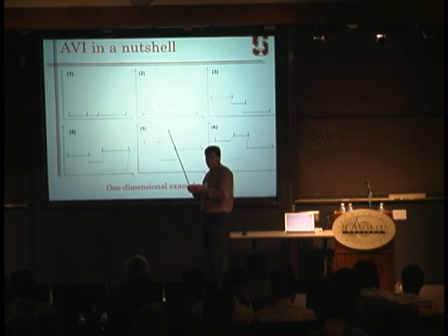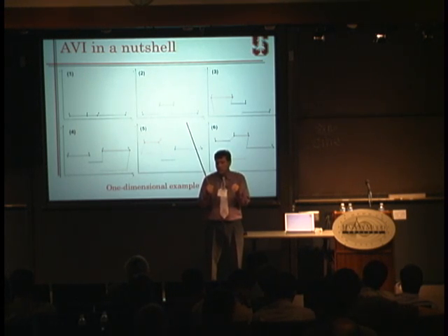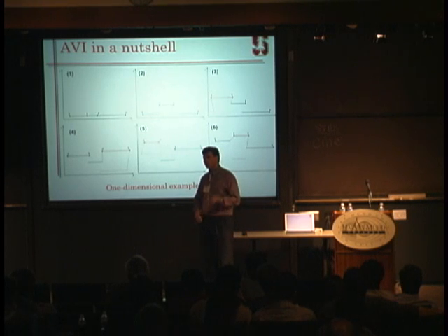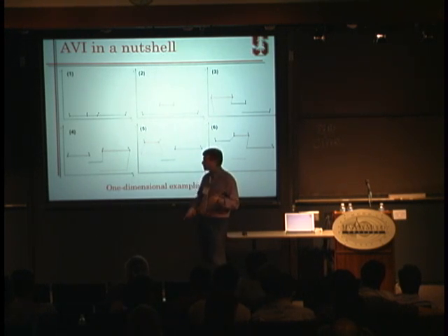At that point, you have deformed your element. So you have pulled the spring, and there will be forces that will try to restore the spring to its natural position. So you use those forces to kick the masses. It's like hitting them with a hammer, and they will automatically change the velocities of the masses. It's like a ball in contact with a wall. It reaches the wall, and it changes the sign of the velocity right away. Okay? So after this step, you'll have 2 new velocities in your 2 nodes.